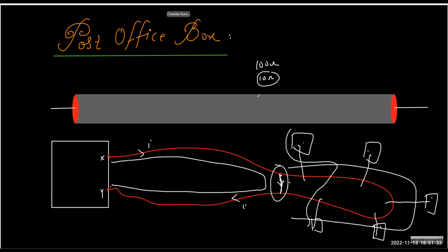Okay. Now let's say I know that 1 ohm per kilometer is the resistance gradient. So 10 ohm means it is happening 10 kilometers away somewhere. Yes. So we know the blueprint of the infrastructure. We know how it is laid out in the city. So if I move 10 kilometers as per the blueprint, I can exactly get the location where this has happened. So I'll dig there itself and take the cable out. Okay. We'll do some checking, a few meters back and forth, and eventually we'll come to the right point.